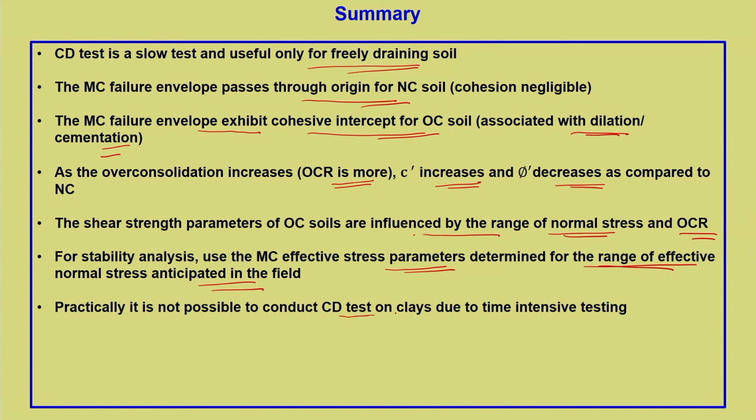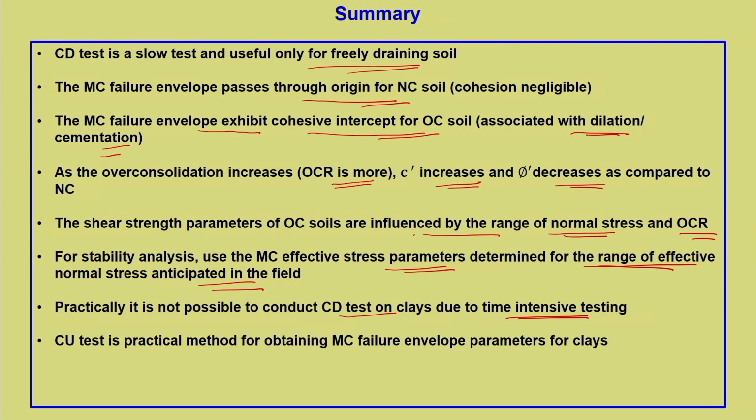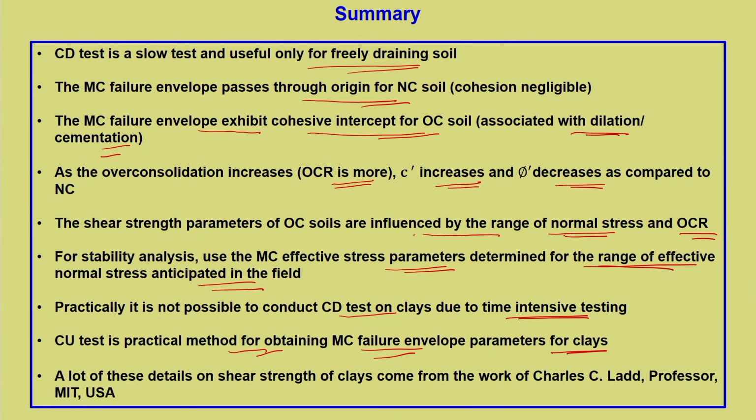Practically, it is not possible to conduct a CD test on clays because it is a time intensive testing. The CU test is a practical method for obtaining Mohr Coulomb failure envelope parameters for clays, provided the rate of shearing is not very high. Now, I just summarize this.